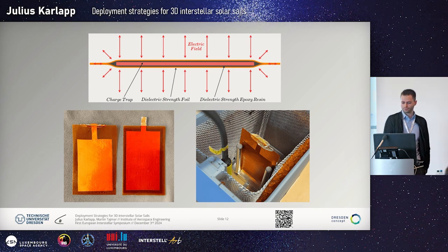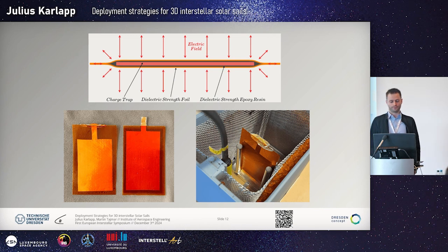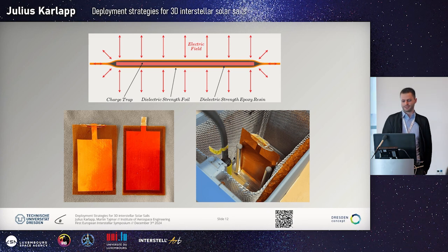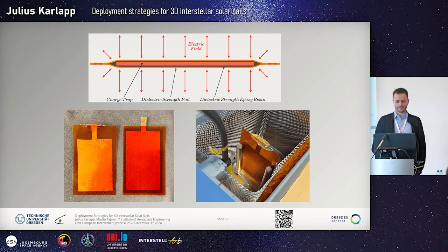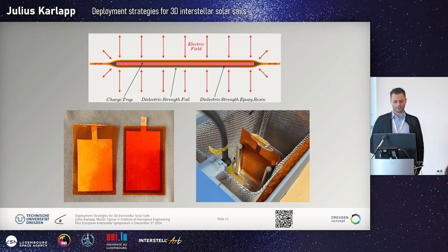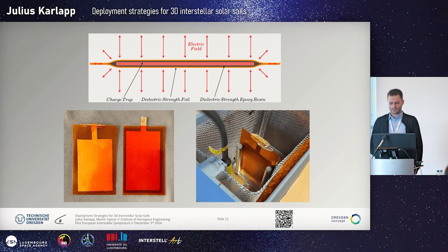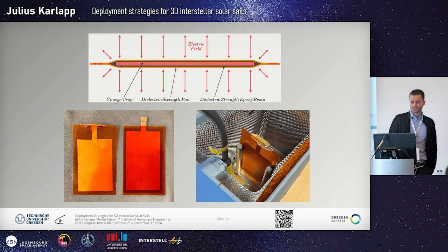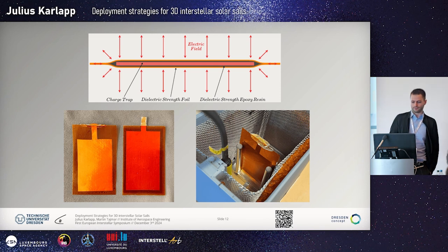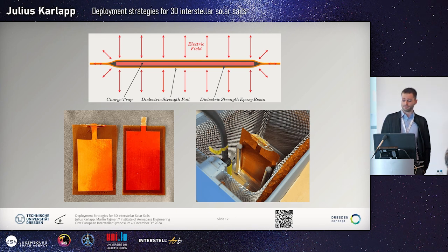In the bottom left figure, you see the prototypes, which have been iterated multiple times to improve the stability of the electrodes. And in the bottom right figure, you can see the test setup we used so far, containing the electrode in the center, the probe of an electrostatic voltmeter to measure the surface potential of the electrode, a grounded cage to minimize the measurement errors from the surroundings, and a layer of silica beads to reduce the atmospheric humidity.